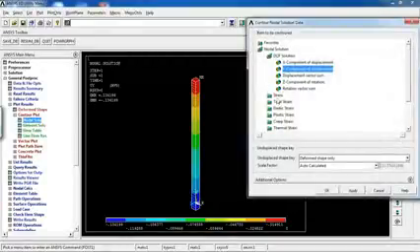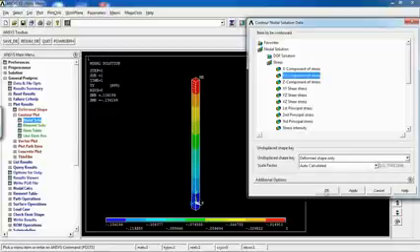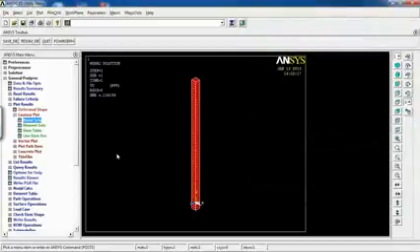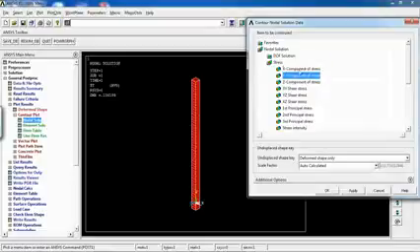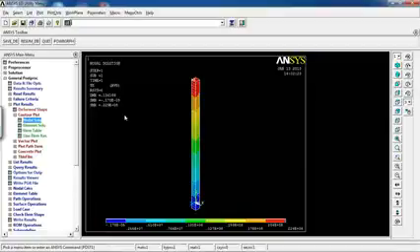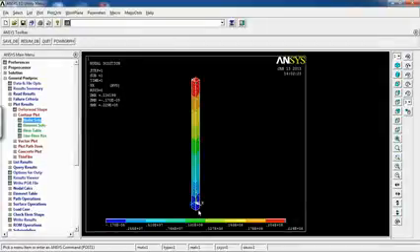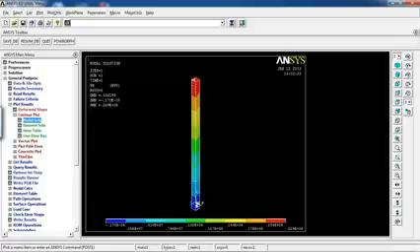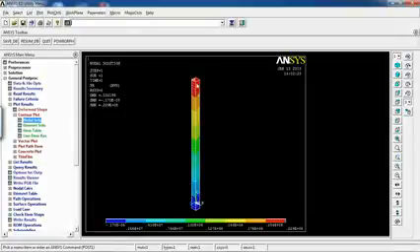And let's see stress in y direction. It's all the same. Stress in x direction, we have some stress in x direction. But I want to point your attention to this case. In this 3D representation, the conservation of volume or mass is not really represented correctly, because according to the conservation of mass, as this beam expands in y direction, it should shrink in its area. But this model is not showing that.